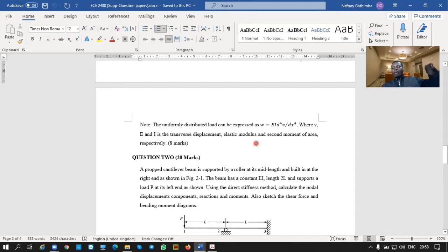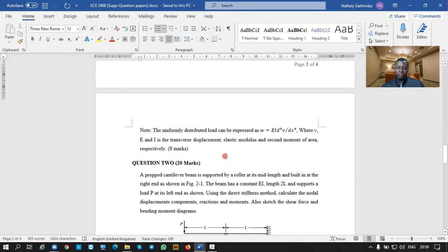So now you should work backward and integrate, because we know the fourth derivative. You move upward, you get the slope, curvature, the moment is the second derivative, the shear force, until you get to the displacement, which is the integration four times. So you'll be having C1, C2, and so on and so forth. Either way, even without being given the shape function, you can start by assuming, and that's always fair.